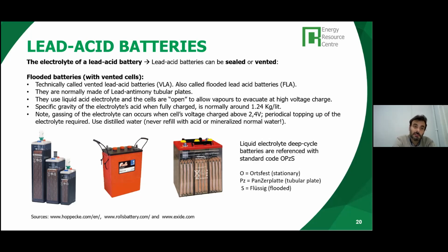Flooded batteries with vented cells, we call them VLA, vented lead acid batteries, or also the flooded lead acid batteries. You can see them as VLA or FLA typically. Normally made of tubular plates for the cathode and the anode, an alloy of lead and antimony. And the electrolyte is in liquid form, and the battery cells are open.